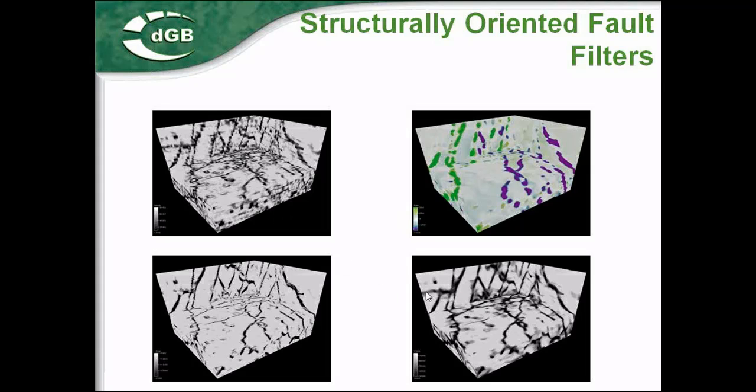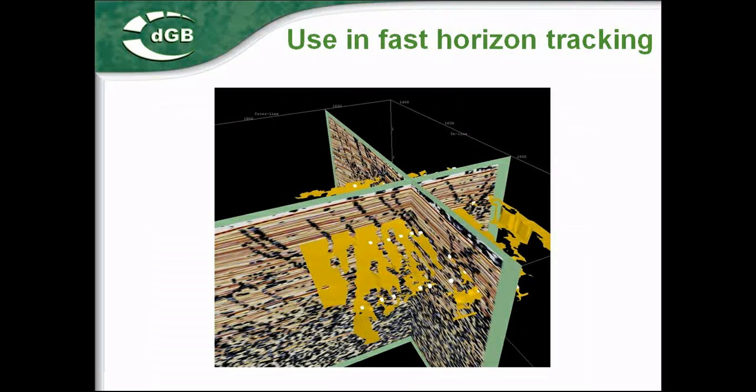And then, for example, here you have an artifact, a discontinuity artifact that's relatively flat. Well, faults are supposed to have a high dip, so you can make a dip conditional filter and say every feature that has a dip that is too low, I remove it. And this is one of those advanced applications where you require watertight faults. Basically, we use the auto tracker here, but we say stop if you come across an attribute value that's so anomalous that it indicates a fault. So with that, you make the interpretation separately for each fault block. So you have to put a seed in each fault block.